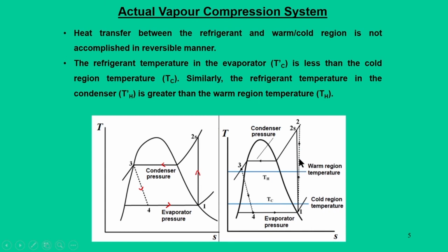It seems that we have introduced the efficiency for the compressors, and we call this the isentropic efficiency of the compressor. The second important aspect of this diagram is that, in an ideal diagram, the refrigerant leaves the condenser at state 3, which is the saturated liquid state, but it may so happen that we can extend it further.